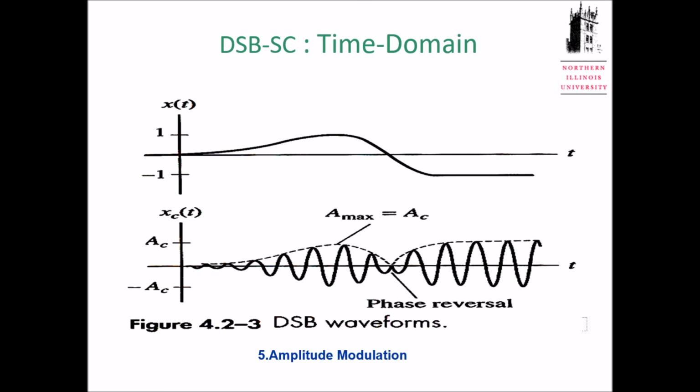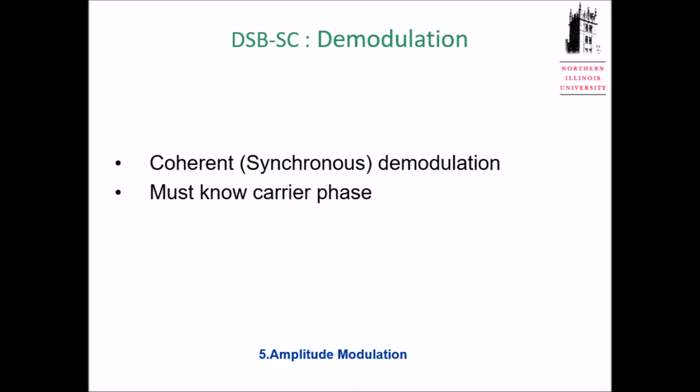So demodulation, as we mentioned before, the envelope is no longer the same as your original message. So an envelope detector cannot be used.